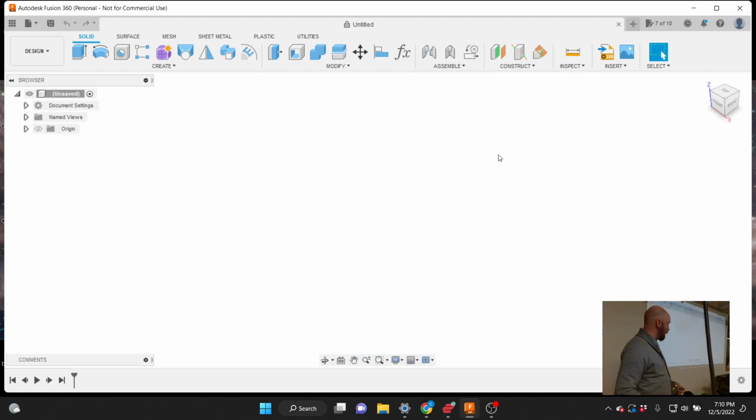In the top right-hand corner, there is a navigation cube. You can see as I hover my mouse over the navigation cube, there are lots of things that highlight blue there. The cube there is how we'll navigate our 3D environment around, how we'll twist and turn and rotate our environment around. Anything that highlights blue, I can click on it, and I'll just be looking at that face. Now, there's nothing in my 3D world right now, so it's kind of uneventful.